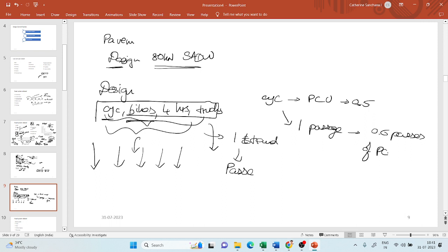So how do we design? If you go back here, if you know pavement design, if I have to take an example, here you will say that, say there's 80 kilonewton load, all the axles will be converted to 80 kilonewton loads, and say if you have some 90 kilonewton passing on the road, you will say that this will be converted to equivalent repetitions of 80 kilonewton.